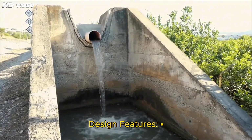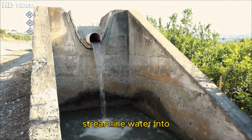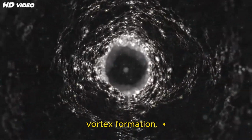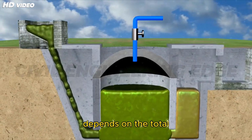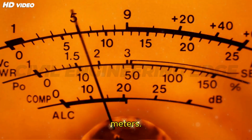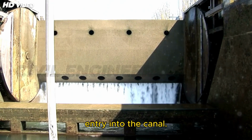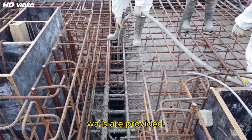Design features: inlet crest, designed as a smooth curve to streamline water into the well. It avoids cavitation and vortex formation. Well chamber: depth depends on the total vertical drop and width on flow discharge. The diameter is usually 1.5 to 3 meters. Outlet channel: designed for smooth re-entry into the canal, reinforcement and toe walls are provided.